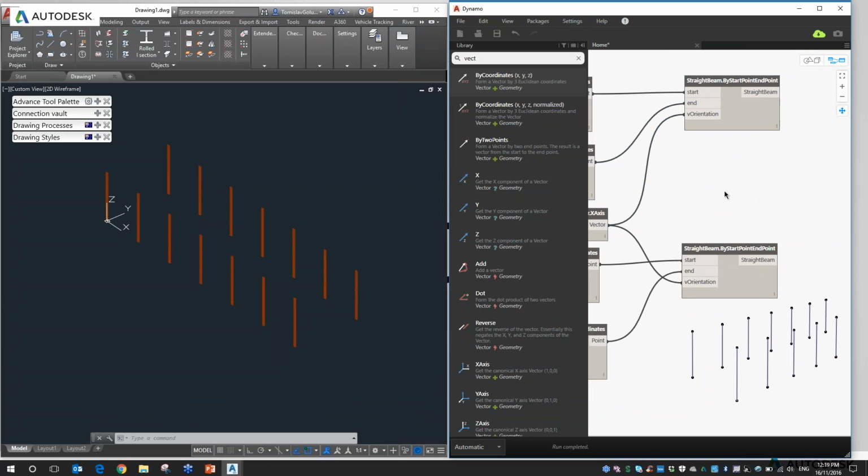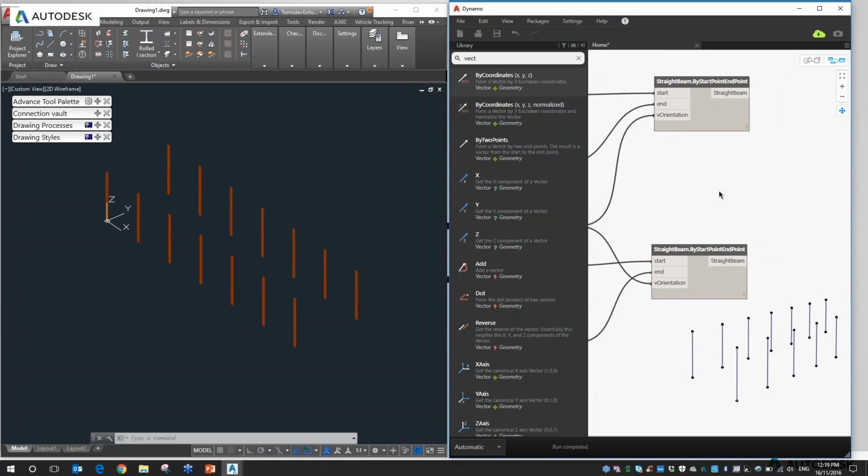So what you want to do with Dynamo is double click anywhere, and it does what's called a code block. So you're going to have to put in inverted commas AS NZS universal column, hashtag at alt 167. Oops, stick it at the end.